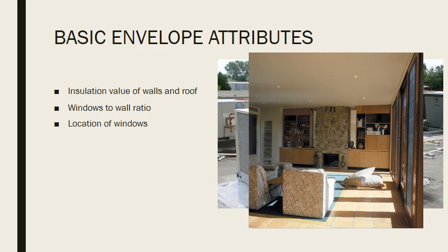But at the same time, we want to have enough daylight come in to reduce the amount of non-natural light needed by the building. The approach we will use, either to have more daylight from windows or more insulated walls and roofs, depends on the location and type of building we will be building, since these factors determine how much external or internal energy load will be in the building.